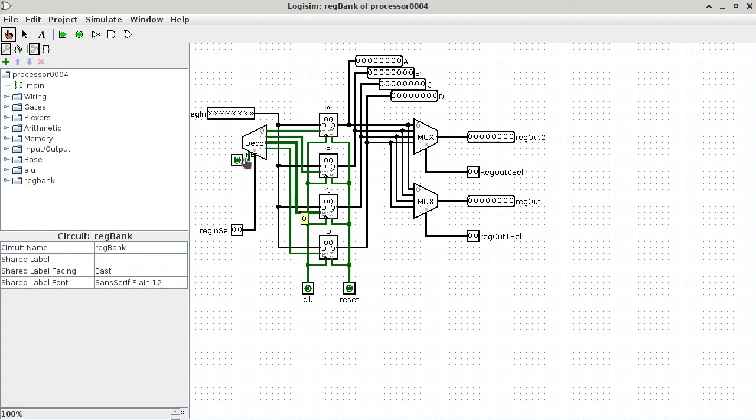And you also have to make sure that the enable here has a 1, because that's basically the same thing as the enable of most devices that we have talked about, and also the control of the control buffer. It basically says, do we actually want to output something? Yes, we do want to output that 1 to the only register that we want to pay attention to. And then we need the clock to go from a low to a high, right? Because we need a rising edge to update a register. And that's it. That's how you update one of the four registers in the register bank.